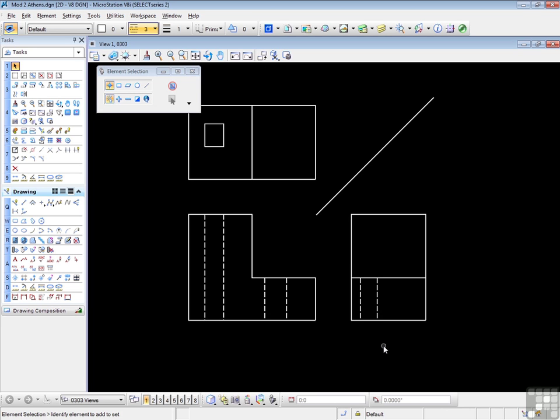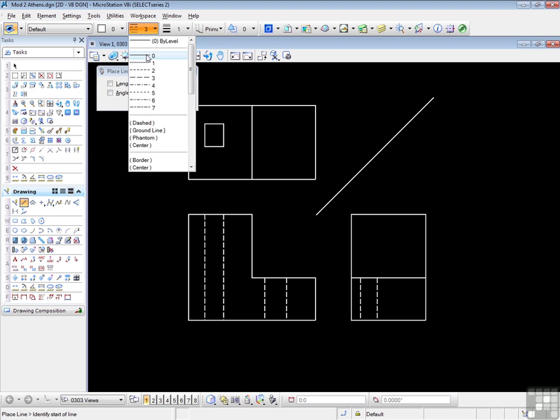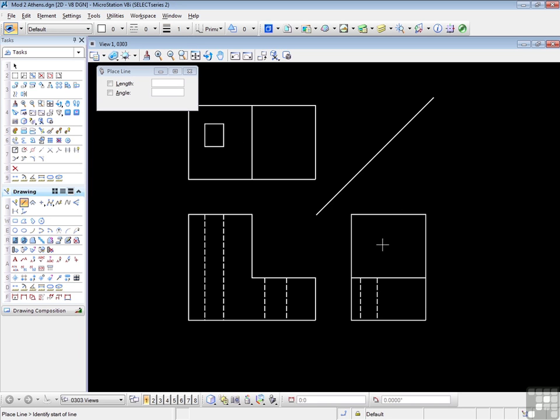Now, when we get up to the plan view, you'll see that we have a slight problem. Line tool is running. I will need a continuous line because it will be a continuous line on the plan view. Let's do this edge first. So I need to locate the center point there, F11, O key, up, enter, and N, find that, O key, come across. Now, before I go down to find this junction, just be careful here because you might well find that the nearest snap is still running. And if I go down, in fact, to the snaps, you'll see that the active snap mode is nearest. Well, I don't want that.